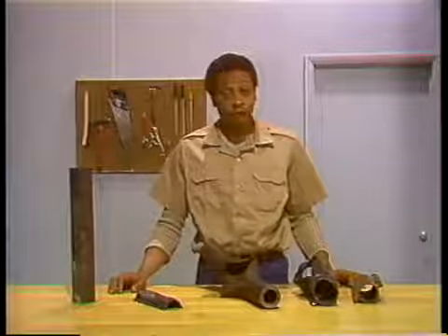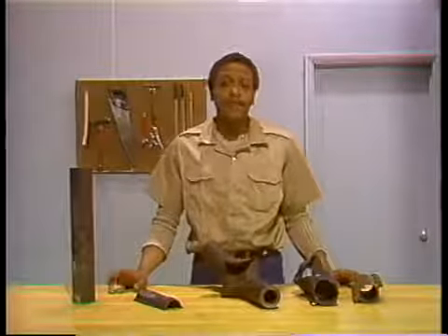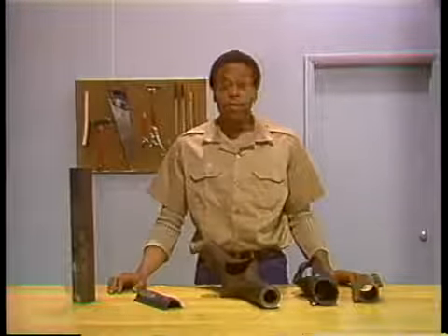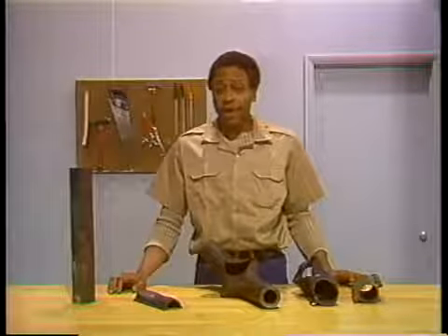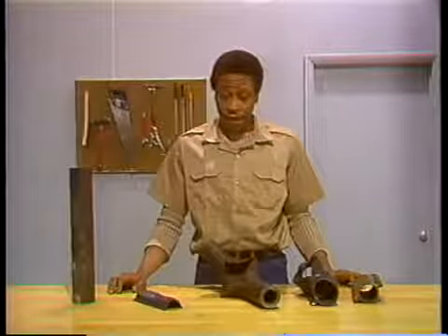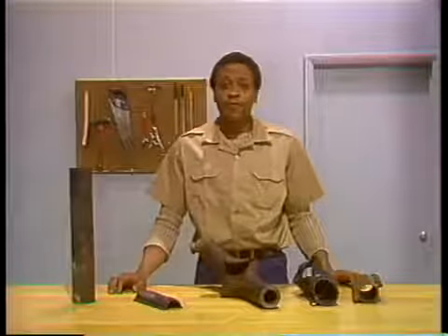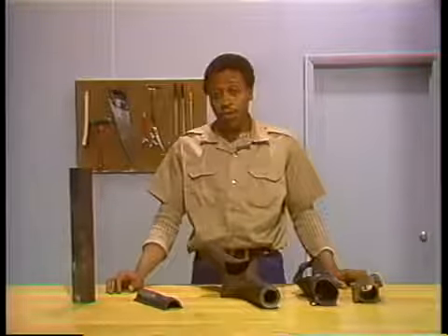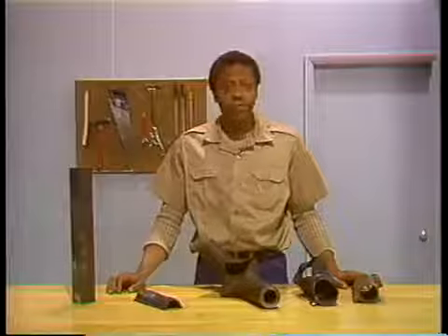Now that we've talked about tube failures, let's take a look at some tube deformities. Deformities, as we said earlier, are irregularities in the tube metal that can lead to failure. The first two types of deformities we'll look at are tube enlargement and heat blisters. Both of these are caused by overheating. Tube enlargement is common in superheater tubes.